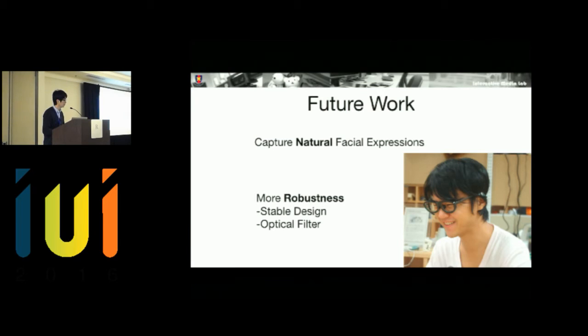Second, we want to improve the accuracy in various scenes. First, as I said before, the device should be personalized for each user. And as the photoreflective sensors are based on infrared, in environments where there are a lot of IR LEDs, the sensor cannot work. So we need to apply an optical filter to reduce the influence.